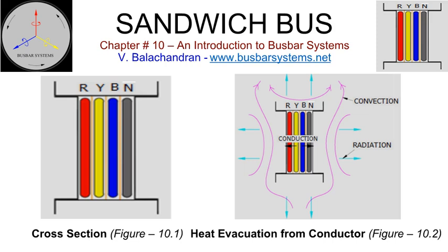Consequently, the temperature rise in the conductor and of the enclosure will depend upon the efficient heat dissipation by the enclosure. The enclosure is made of 4 sections. 2 of these sections are pressed against the stack of conductors, and the other 2 are located at the top and bottom and held with rivets. All the sections are either extruded if made of aluminium or formed from sheet steel.